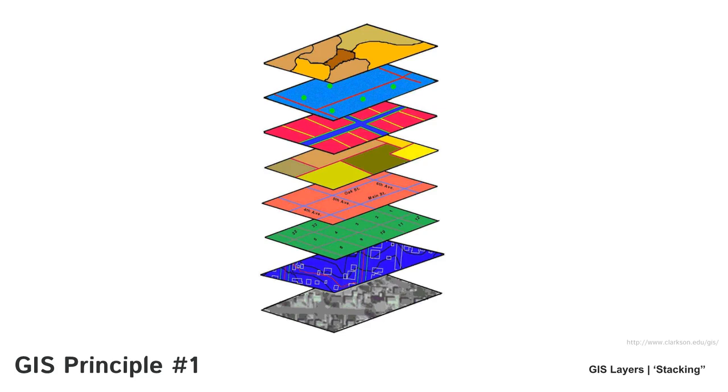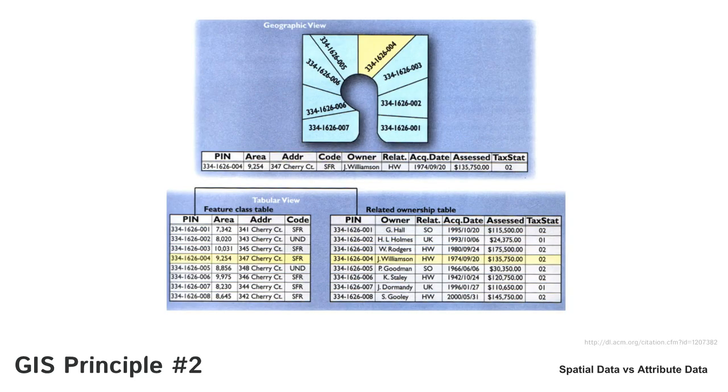And so here we can see the stacks in a more diagrammatic way. These stacks are sitting on top of each other. And importantly, the themes stay separate. So everything that is about land use, maybe it stays on one layer. Everything that's about certain locations, it's on another layer. Everything that relates to, say, an image, like a satellite image, that stays on another layer. So we can keep the layers separate, but they can be in the same space together. So that's that concept of GIS stacking.